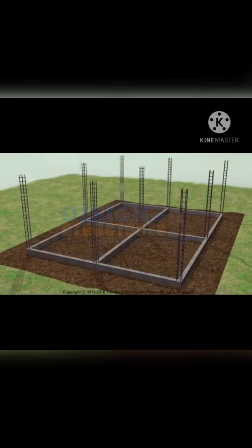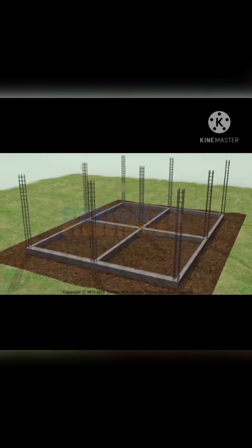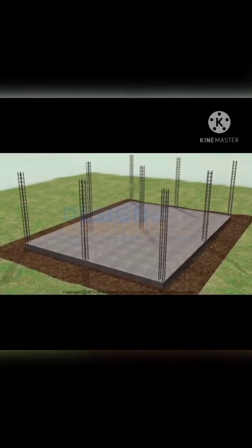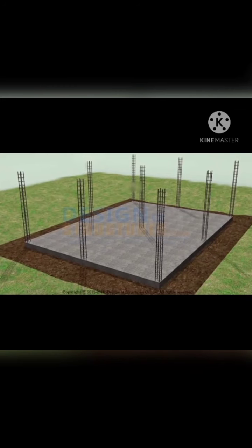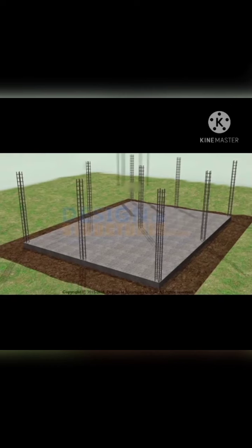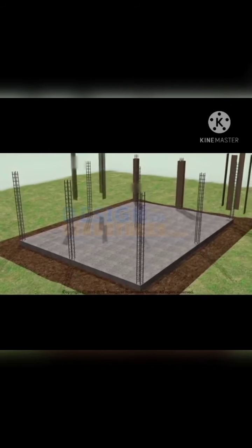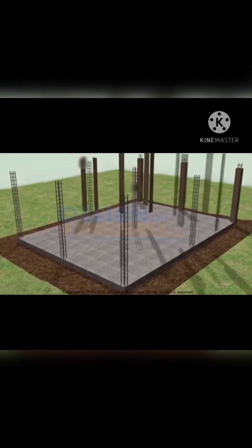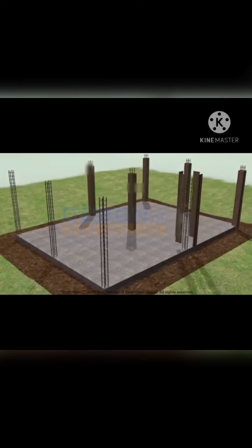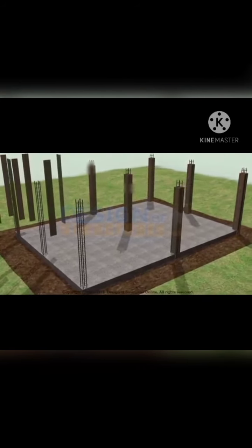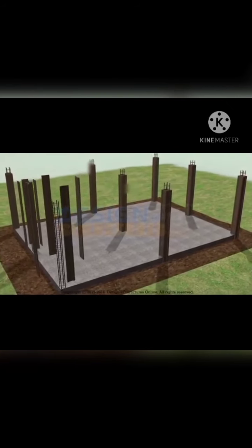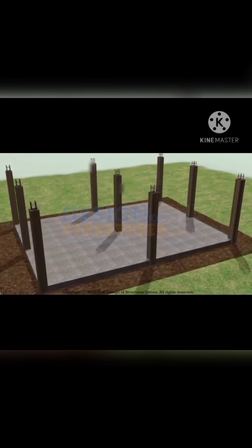Slab concreting. Grade slab requires no reinforcement as it's resting on ground strata itself. Top of plinth beams and grade slab should be at the same level. Column shuttering. Column shuttering should be rigidly constructed and efficiently propped and braced both horizontally and vertically, so as to retain its shape. The shuttering should be set accurately to the desired line and levels should have plane surface.